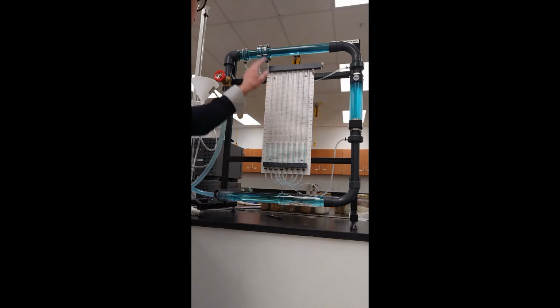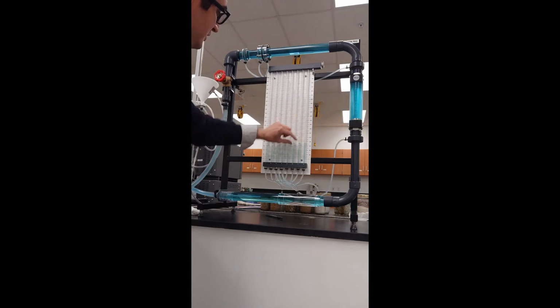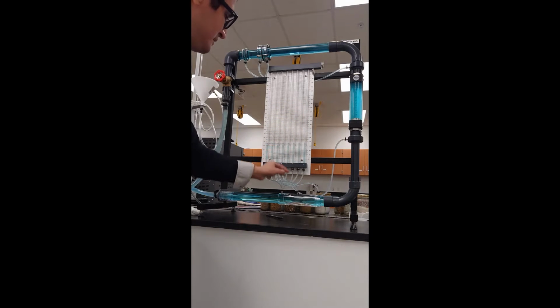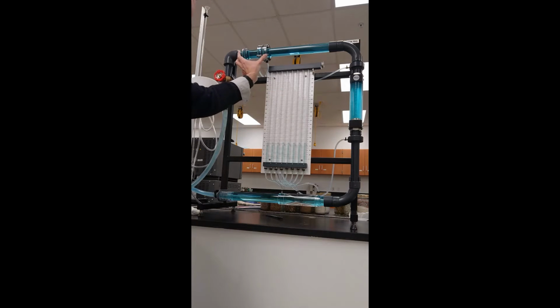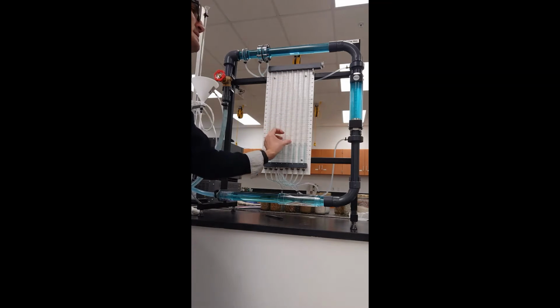The same concept applies to the orifice plate at the top. Manometers 6, 7, 8 represent the orifice plate. 6 and 7 show the pressure difference across the orifice plate, and 6 and 8 show the total head loss within the orifice plate. The middle two, 4 and 5, stand for